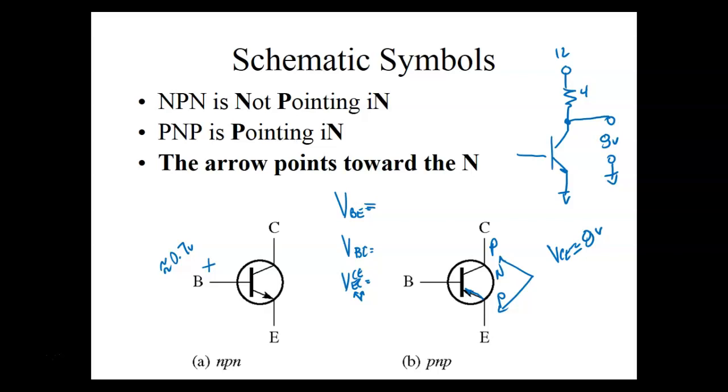It's going to be hard to get exactly 0.7 of a volt, so normally we would put a resistor right there, put some voltage over here, like 5 volts, and figure out what size resistor I need to drop around 4.3 volts, and then we'd have current flow.